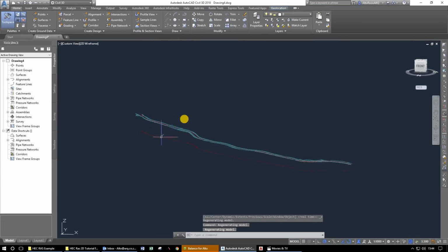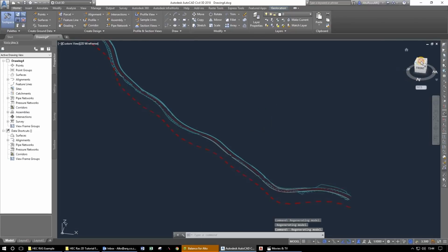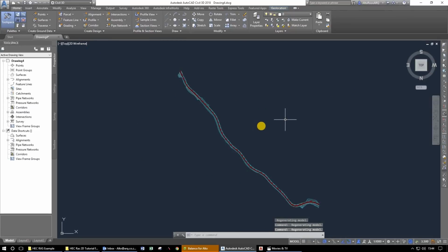As you can see, it is relatively 3D, it's not a perfect model, but hey, this is what we got from somebody else. Just to confirm that this is actually in the correct position, we will be using satellite imagery from the Bing server just to check that it is actually in the correct place. The way you can check that is by typing in GEOMAP, and then we would like the aerial one. For this aerial map to work, you will have to be logged in, and you will have to click allow online data to be used.